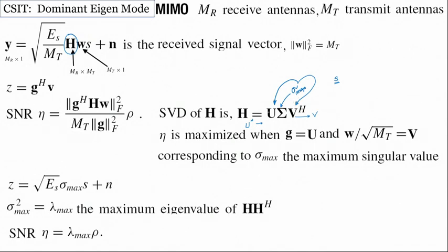for processing. So, that particular one is used in the G, whereas this one is used in the transmitter. So, the vectors are formed accordingly. At the transmitter you have W, which is defined below, and at the receiver you process with G. So, G Hermitian with U makes it 1 for this entry, because that is what we are doing. At the transmitter side, since we are sending only one value and there is only one column of the vector being unitary, this also leads to 1 and hence there is sigma max.